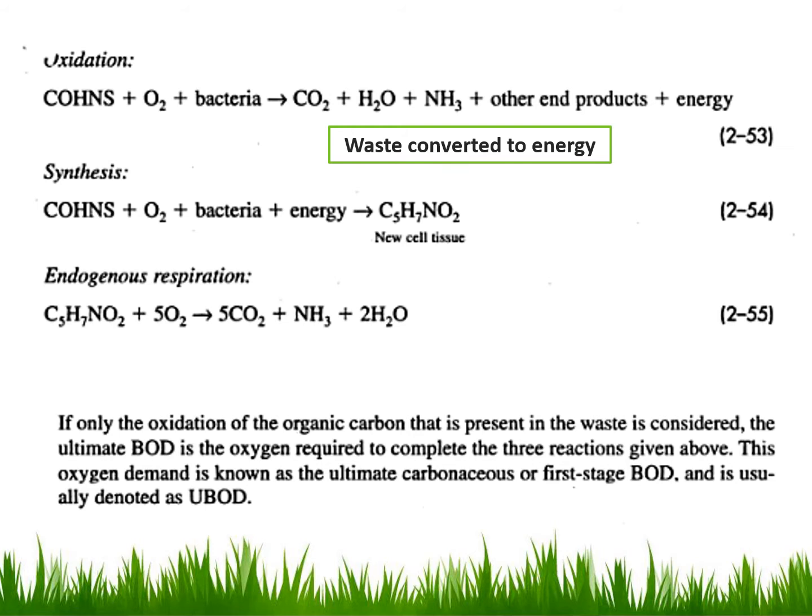So if only the oxidation of organic carbon that is present in the waste is considered, the ultimate BOD is the oxygen required to complete the three reactions given above. This oxygen demand is known as the ultimate carbonaceous or first stage BOD, and is usually denoted as UBOD, ultimate BOD.